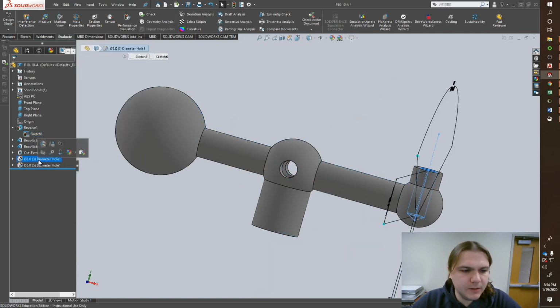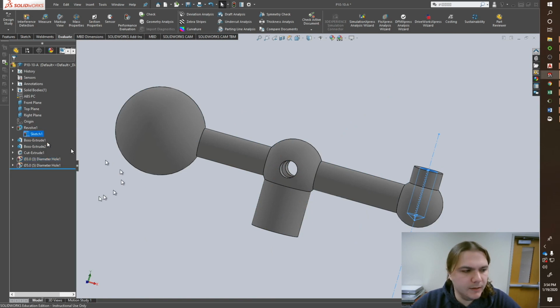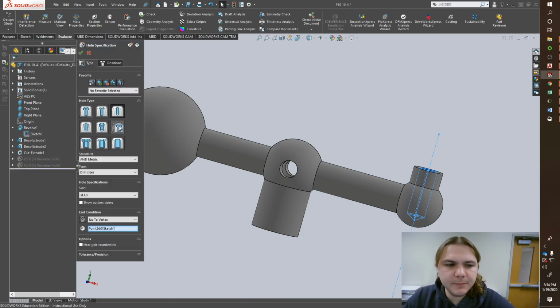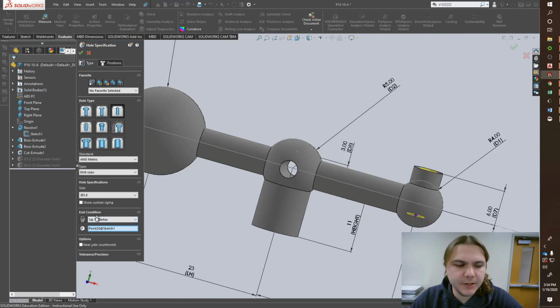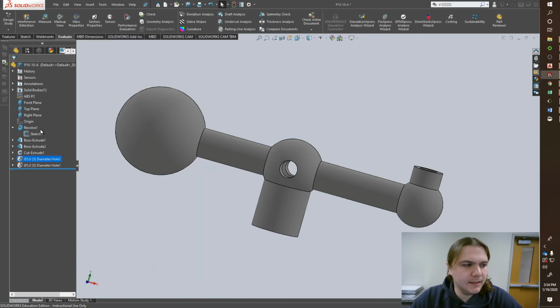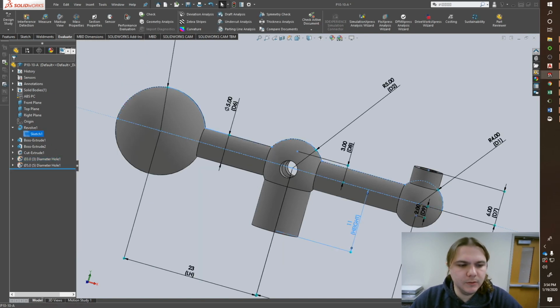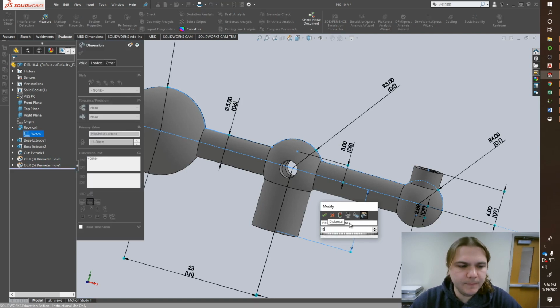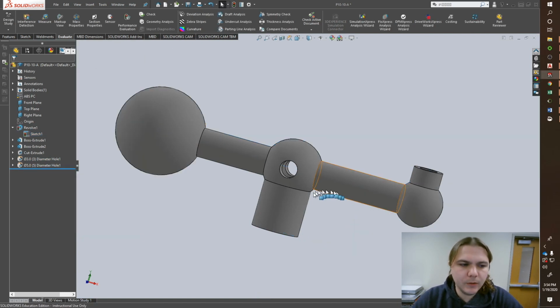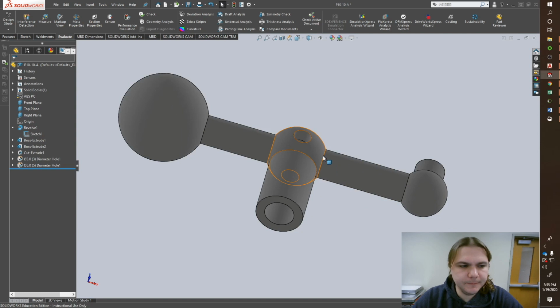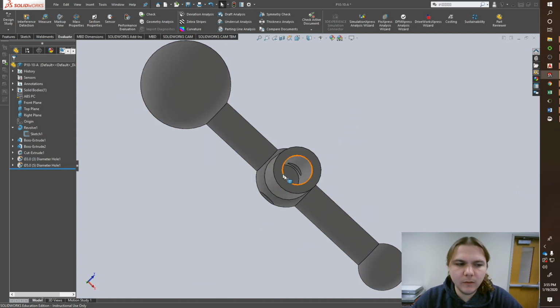Then when I went to create my hole feature, there's an option for the end condition being blind, meaning type in the number, or up to vertex, meaning I was able to click on that point in the sketch and have that hole there. So whenever I change my height, say to 15, I don't have to worry about changing that hole depth as well.